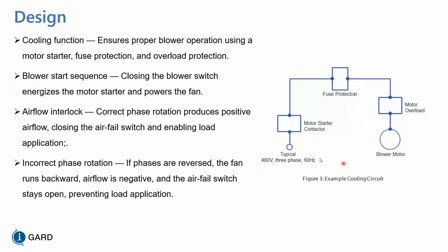Cooling functions. Obviously, you have a blower motor, and depending on the load bank, you can have multiple blowers in there. You have overload to protect the relay, fuse protection, and a starter. We have load banks with internal power and some load banks with internal and external power capabilities. So if you wanted to test single phase power on a 3-phase load bank, you can do that. You just need to worry about providing 3-phase power to the blower so that you could maintain the cooling of the system and not overheat your resistors.